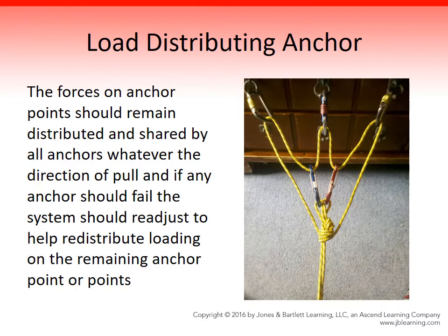And if any anchor should fail, the system should readjust to help redistribute loading on the remaining anchor point or points. It is also important to note that no anchor system can be made completely self-equalizing, and it is critical that all rescuers realize that load distributing anchors are not for casual use in rescue. Because of their complexity and potential for failure, these systems should only be used when there are no options such as load sharing or extending anchors.